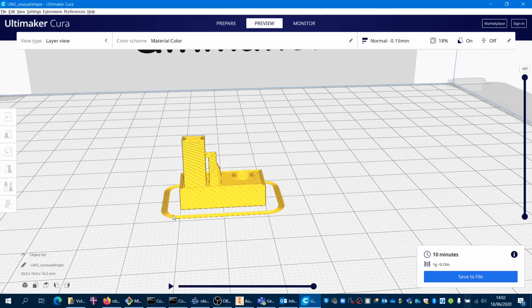Firstly, it makes sure the printer nozzle is not blocked and it's printing nicely and the material is flowing freely. Secondly, it helps you to see that all the part will fit onto the bed. This is a very small part, but if you had multiple parts or a much bigger part, it will draw this first, and you can see straight away if any bit sticks off the edge of the bed and the part won't print. It's a good clue for that.